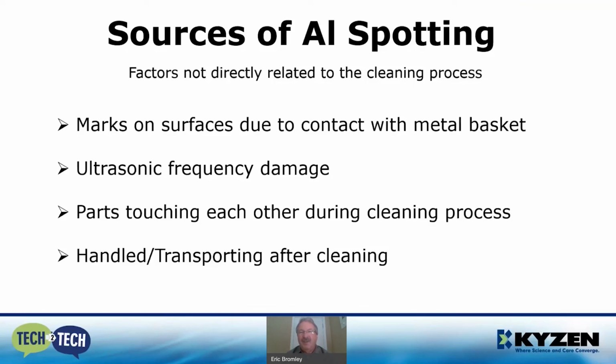Handling and transporting after cleaning can also cause some spotting too. If you remove the parts from the cleaning process and put them into a dirty basket or a dirty transport method, or you're moving them around with dirty hands, you can put some spotting back onto the parts and really cause damage that could be prevented for sure.